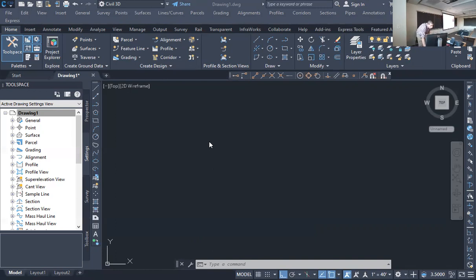If you scroll down the list, see here, SPCPAS. Anybody know what that stands for? State Plane Coordinate System. So it's state plane coordinates. Pennsylvania, South Zone. So in Pennsylvania, it's divided into two zones, North Zone and South Zone. We'll talk a little bit more about that later. But you're in Pennsylvania state plane coordinates, PA South Zone.